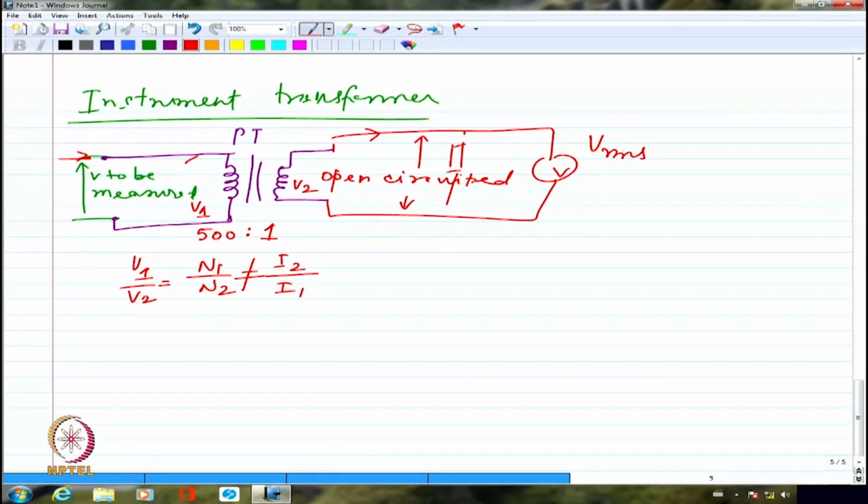You are just measuring the voltage. You don't want to connect your voltmeter as a load, do you? So if you don't want to load it, you better not draw a tangible current. The current drawn should be as minimum as it can be. So I am telling that it has to be as good as an open circuit. That's all. Got it?